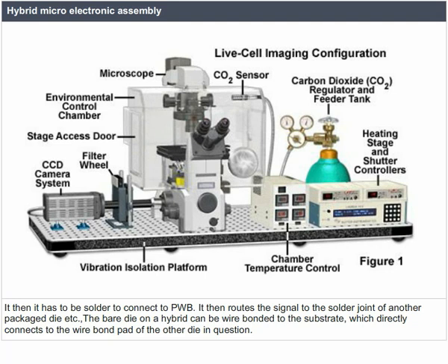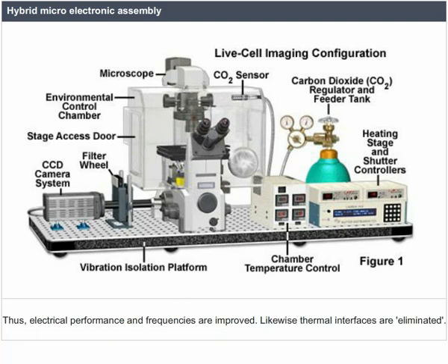The bare die on a hybrid can be wire bonded to the substrate, which directly connects to the wire bond pad of the other die in question. Thus, electrical performance and frequencies are improved. Likewise, thermal interfaces are eliminated.